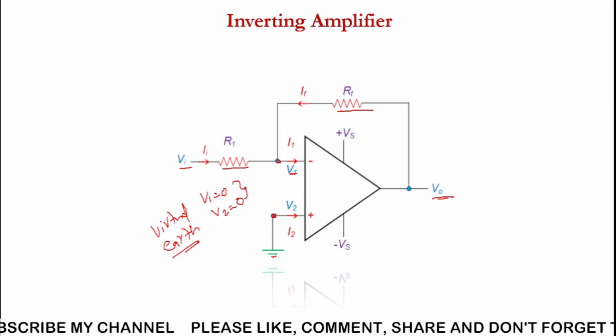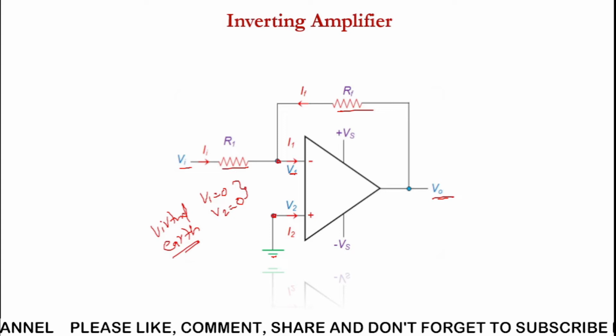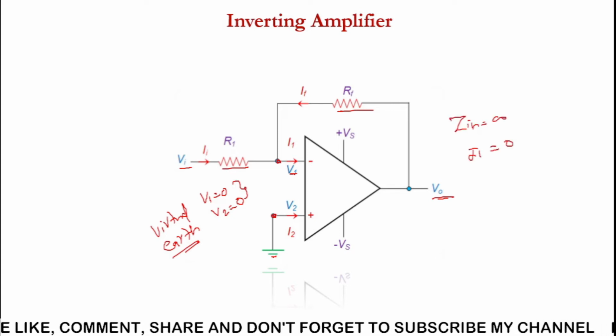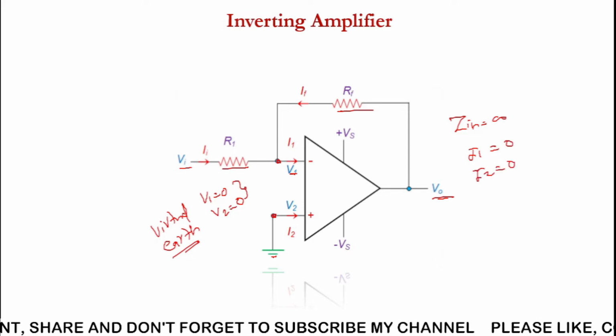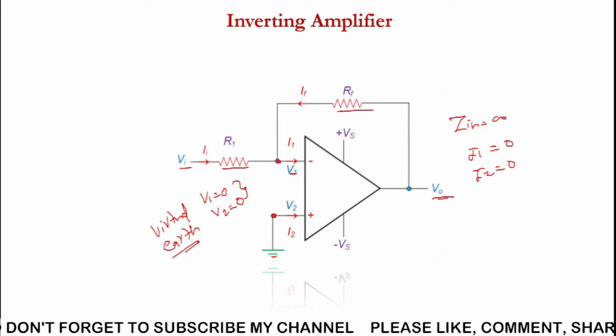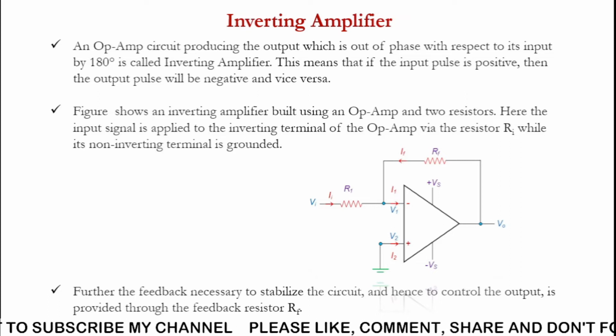So how do we find the gain of this inverting amplifier? We have to do it mathematically. For that purpose, you should know the virtual earth concept, where V1 and V2 are both equal to 0 and Zin is infinity, so the currents I1 and I2 flowing through the inverting and non-inverting terminals are both equal to 0. You can see here, this is the circuit of the inverting amplifier.